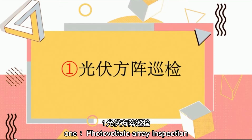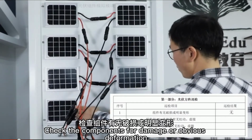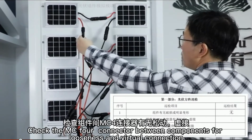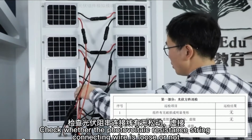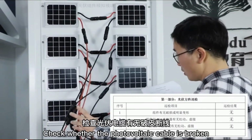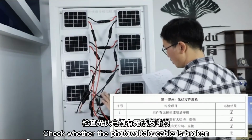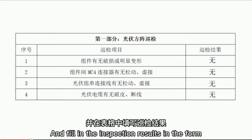1. Photovoltaic array inspection. Check the components for damage or obvious deformation. Check the MC4 connector between components for looseness and virtual connection. Check whether the photovoltaic string connecting wire is loose or not. Check whether the photovoltaic cable is broken. And fill in the inspection results in the form.